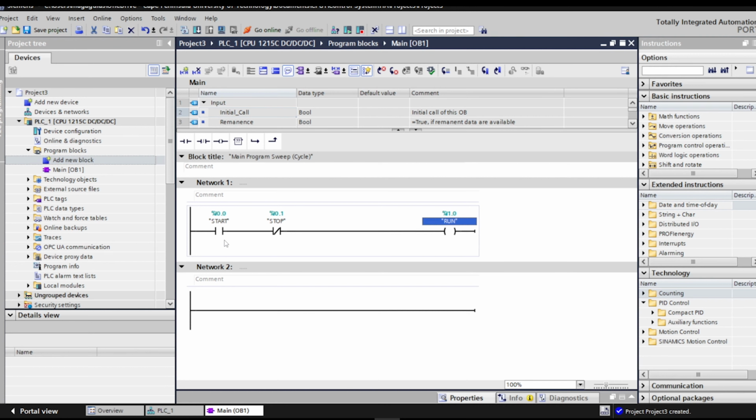Now with this, you start, you close, because remember we said this is your power supply, 24 volt or 12 volt depending on your PLC. From this way going this direction, it always goes like this, from here to here, go here, not backward. So when you close here, press start. Remember, these are push buttons. When you press and release, it will be on. Once you release, it will be off.